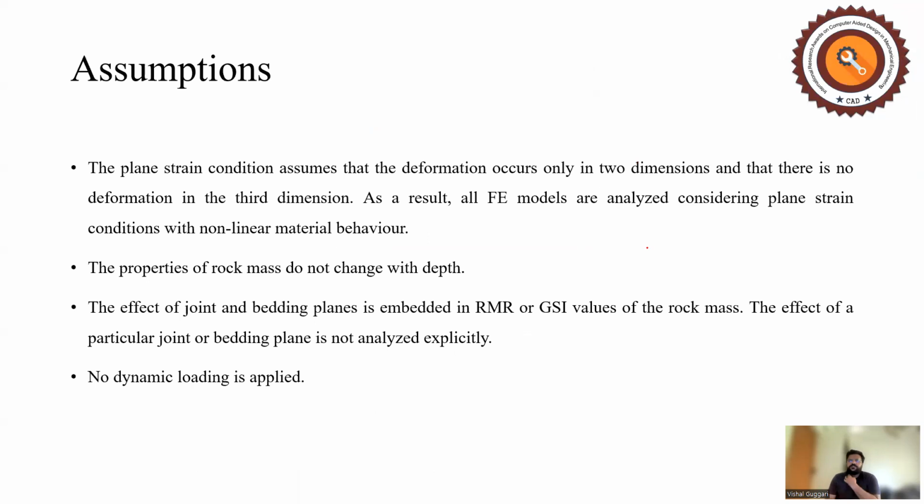A few assumptions have been made during the simulations. The plane strain condition has been assumed because it is a 2D problem, in which the plane strain condition assumes that the deformation occurs only in two dimensions and there is no deformation in the third dimension. And the property does not change with depth. If you consider a single model, it has a cumulative single property, but it does not change along with the depth.